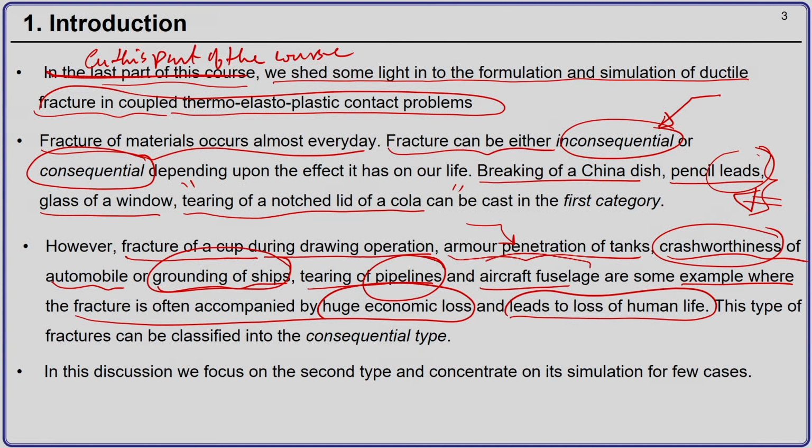So, also aircraft fuselage. An airplane goes up in the air. It goes from atmospheric pressure where the cabin is depressurized, it goes up where it is pressurized, it comes down, lands, it is again depressurized, and the same cycle goes on and on for many times, and this kind of loading, that is this kind of fatigue loading, may cause problems in the fuselage. And nowadays a lot of companies are focusing on thinner and thinner material, trying to reduce the weight of the aircraft.